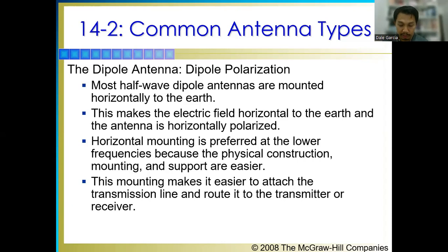500 kilohertz is a common operating frequency in AM broadcasting. So, speed of light divided by 500 kilohertz is almost 600 meters. Divide that by 4, 150 meters. So, how tall is 150 meters? It's already tall, no? 150 meters, how many stories of building is that?